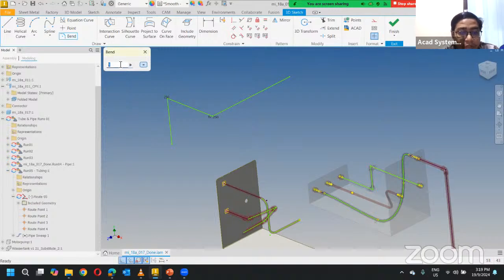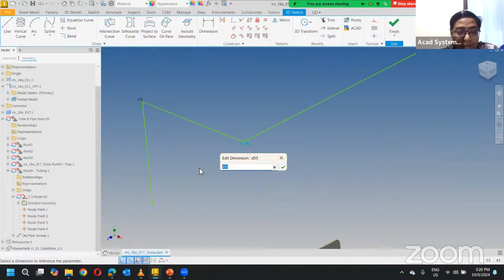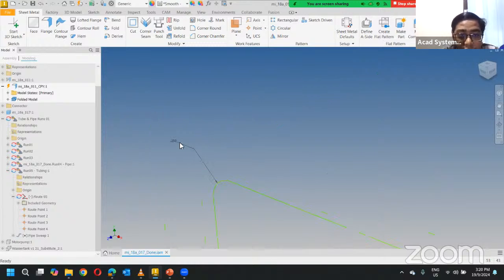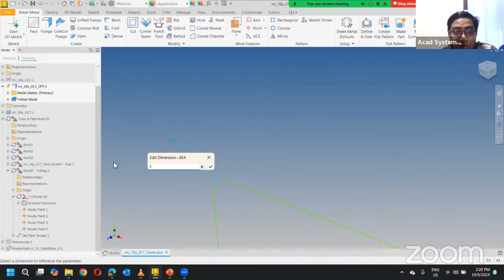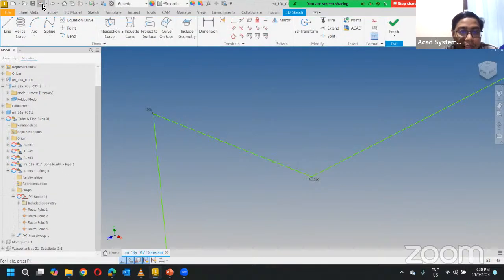Okay, I think 5 may be slightly too large. I'm not sure why. Okay, it's already created. Let me just edit the value from here. This one, let's say 5-inch. Click finish. This one, okay, actually this one I don't want. So let me just set this one to 0. Okay, because it's automatically added when I create. So let me just undo this one instead.